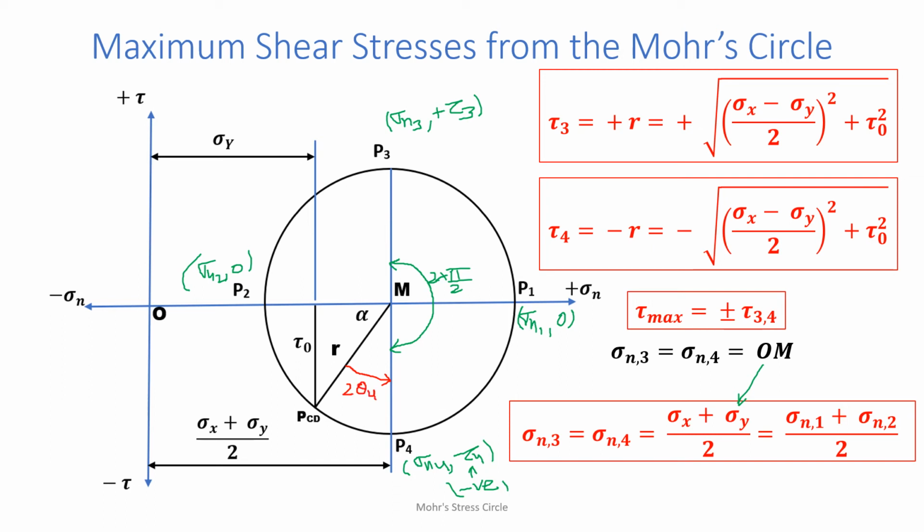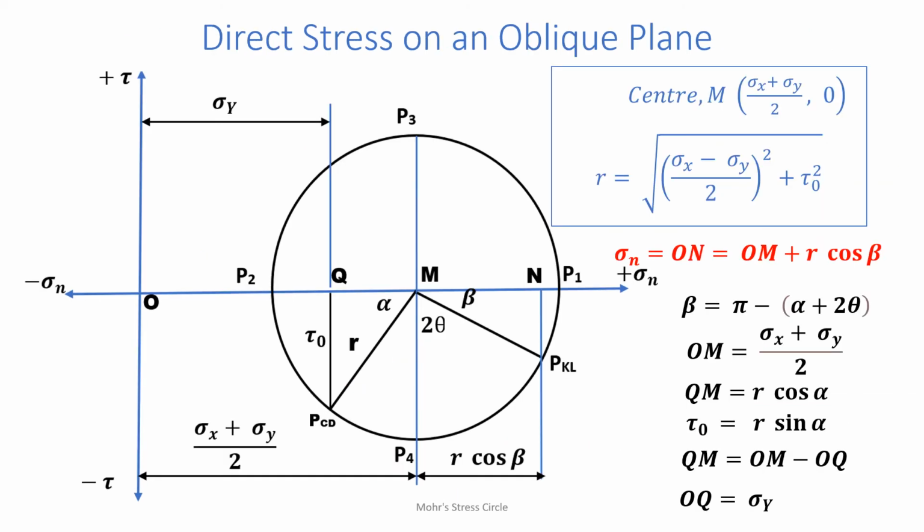So basically in the Mohr circle this angle will be double. It means we will measure 2 theta 4, take half, and we know theta 4, so we will know the maximum shear stress plane P4 with sigma n4 and tau 4 stress values, anti-clockwise at an angle theta 4 from PCD. Theta 4 is half of this measured. The proof we are doing in the next slide.